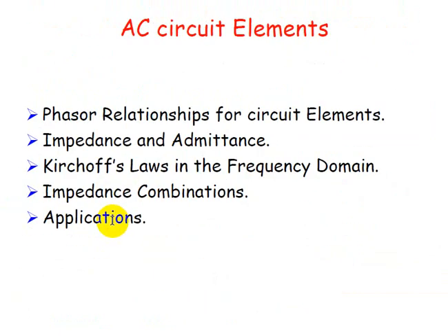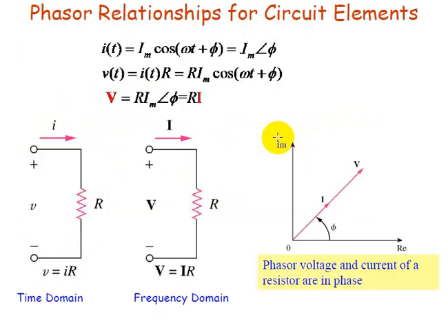Let's start with the phasor relationship for circuit elements. We need the phasor relationship because if we discuss any circuit element in the frequency domain, which is the phasor representation of complex numbers, our analysis will be easier. We will analyze the circuit in a better way, it may take less time, and the mathematical complexity will be minimized if we analyze the circuit in the frequency domain rather than in the time domain.